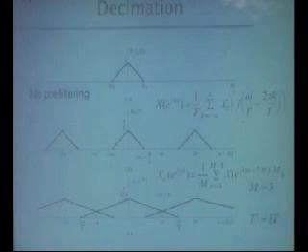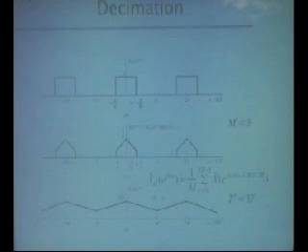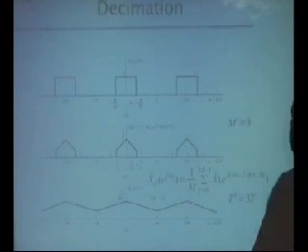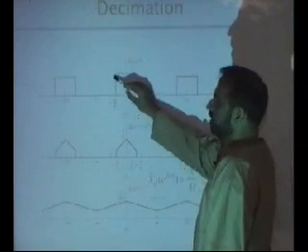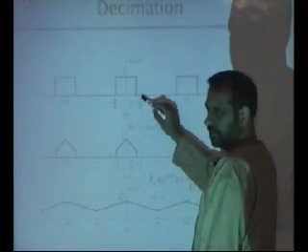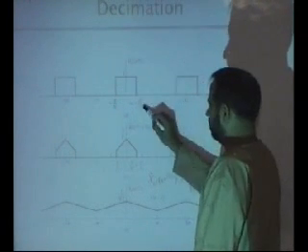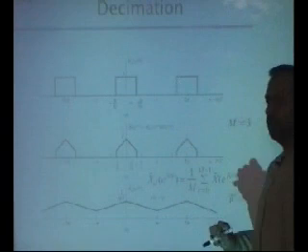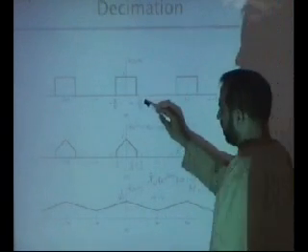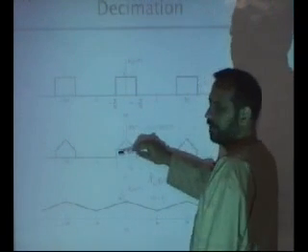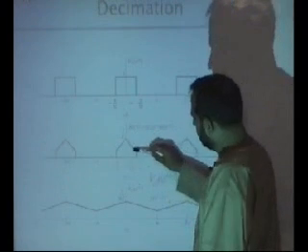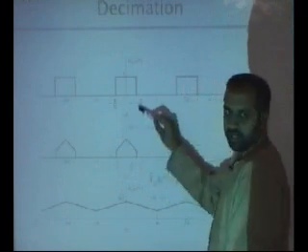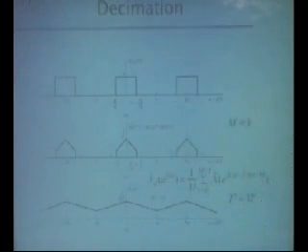So this is a simple rule which says that if you want to do that, first use a pi over m digital filter, design it in MATLAB, pass it through this pi over m filter, cut what is not required, otherwise it will alias and corrupt this part of the spectrum, and now you downsample it by 3, right?